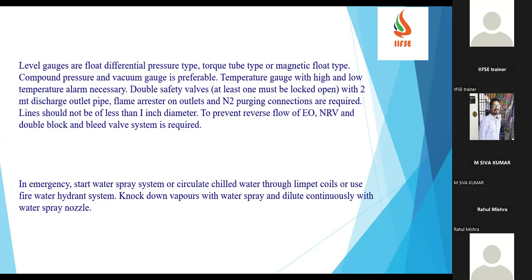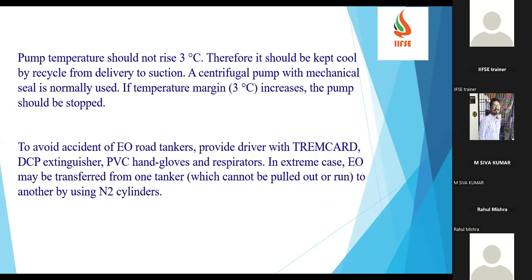Then in any emergency, start the water spray system, or circulate chilled water throughout the limpet coils, and also use the fire hydrant system, knock down the vapors with the water spray, and dilute continuously with the water spray process. This is the action we can use in case of any emergency.